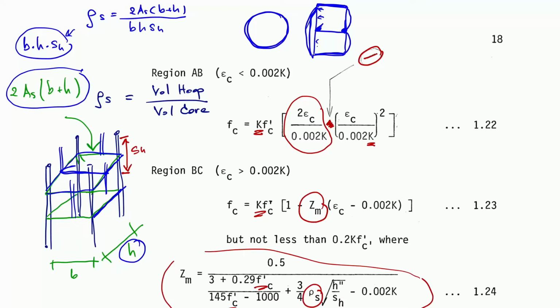This has less stiffness if you look into that view. The confining effect relies on the stiffness of the hoop system. So you will need to incorporate this steel into your calculation if you have something aside from the rectangular shape hoop.